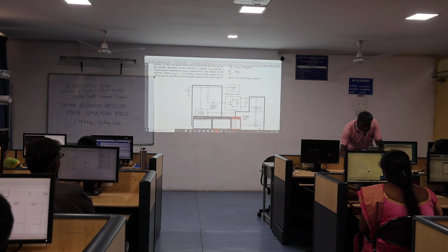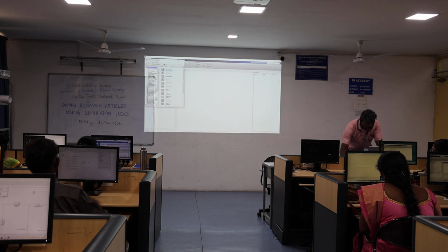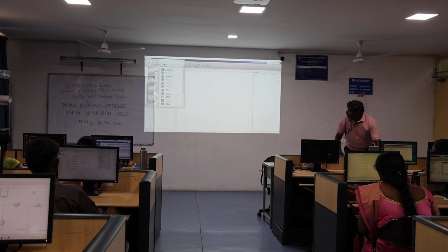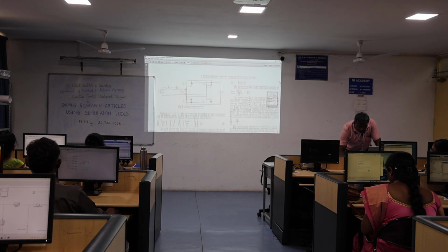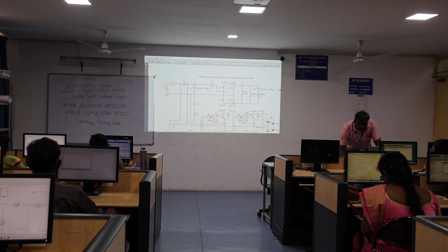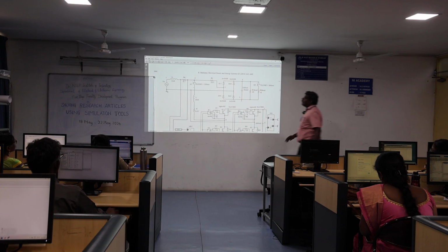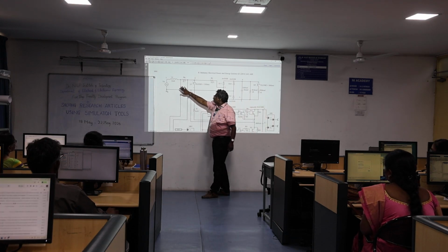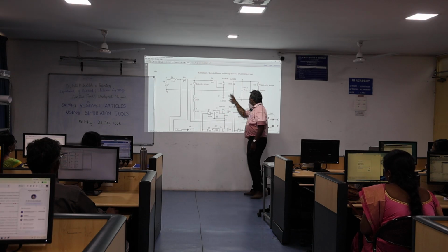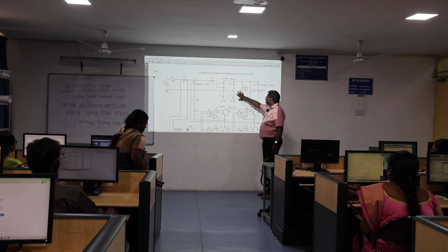So now we can go for MATLAB. Again go to the Simulink library browser. I want to construct first one of the shunt active filters. So now we have a source here, right? We have a source inductance and resistance. Again you have a non-linear load. I already told you, you can use a diode rectifier.